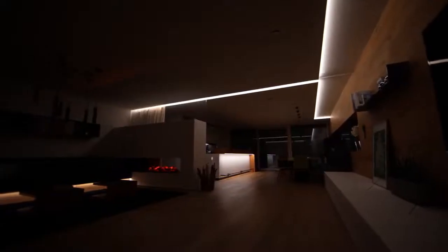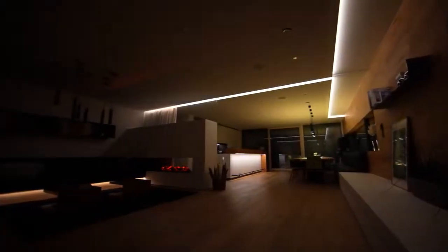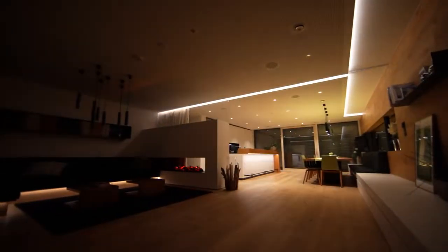The second way is to invert the behavior of the touch. So a single tap in the kitchen mixes the mood in or out, rather than a long press. How a touch behaves can be set within the Loxone Config. By the way, we will go into all these topics in our next episode. If the behavior of the touch has been inverted, then a longer press will be required to scroll through the various lighting moods.